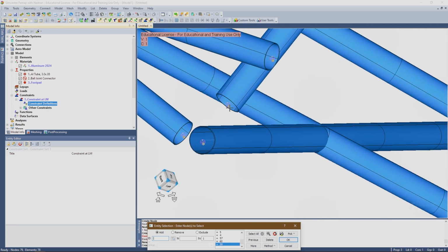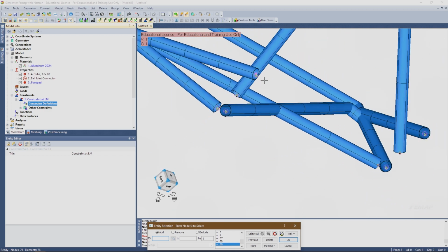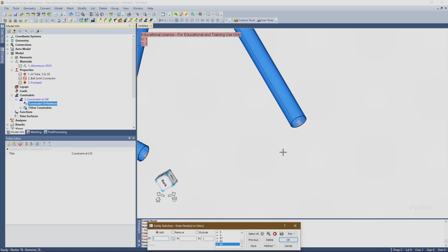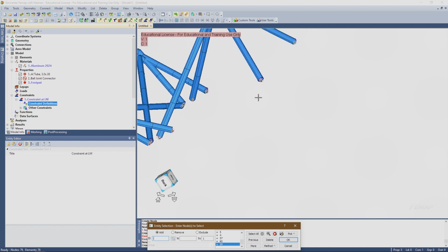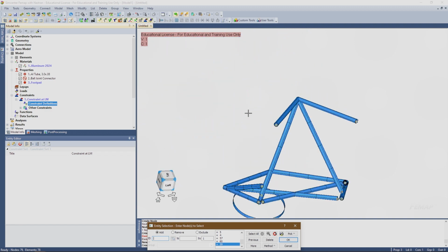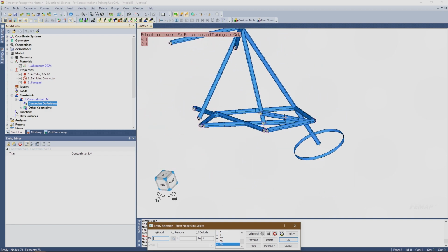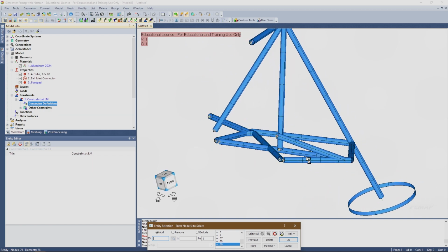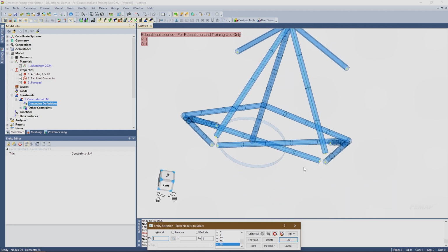Essentially you just represent your joint like this, you get the force on the joint, and then you can take that into a hand calculation spreadsheet to calculate your joint bolt failure, your lug joint failure, whatever. So that's another huge benefit, that they're very easy to get forces from.